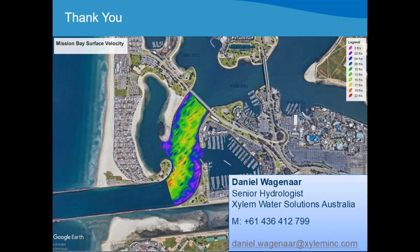Okay, Daniel, thank you. And on that note, here's another question. Does it work only in shallow depths? I would like to know whether the instruments work at more than 3,000 meters. All right, so these acoustic Doppler current profiler instruments, ranging from, as I said, 3 megahertz to around 250 kilohertz, are your traditional instruments that are used, and I would almost say 250 is a bit low.